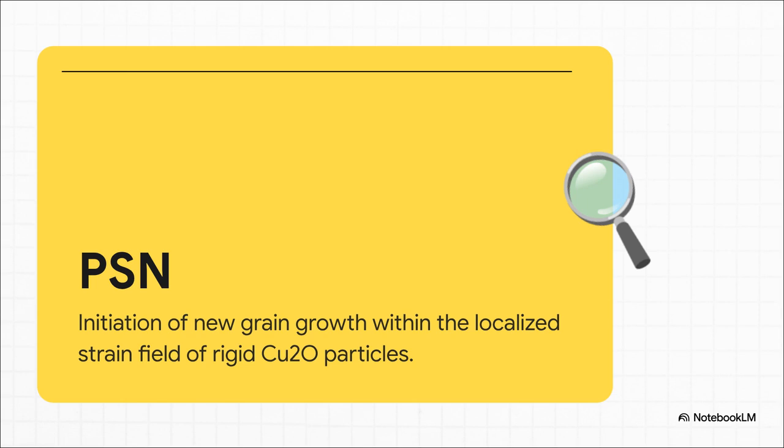They act as rigid barriers and critical stress concentrators. This forces an extreme localized strain field, what we call the particle deformation zone, which then dictates the exact specific nucleation sites of new, fine grains.